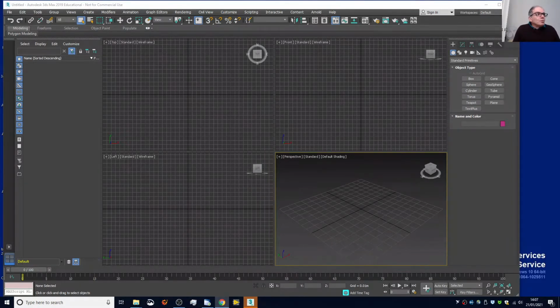So if you want to animate one object which is within the whole group, you can select the object, do the animation, then go back. If you want to do that, it's better to do it using linking, as I said, and I will repeat that, it's better to do it using linking.